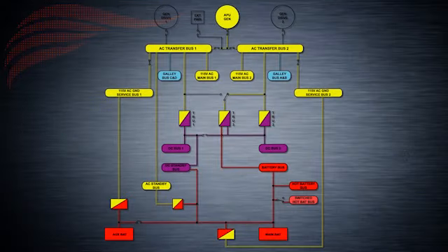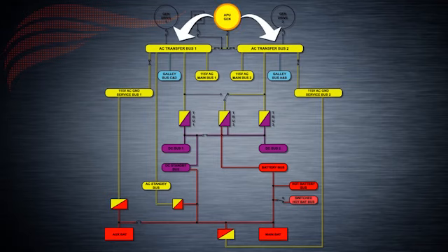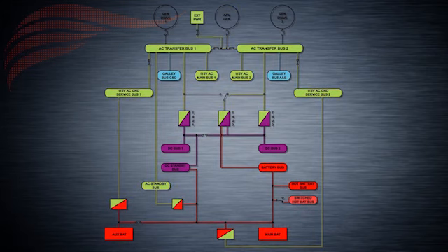Moving on, during times when the engines are shut down or faulty, the APU may supply the electric demand of both AC transfer buses. This is guaranteed to work on ground, but during flight, it works only according to the altitude limitations we outlined earlier. Similar to the APU, external ground power may also supply energy to both AC transfer buses. The receptacle is located in the lower right forward fuselage, near the nose gear wheel well.